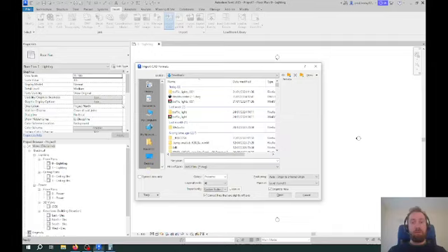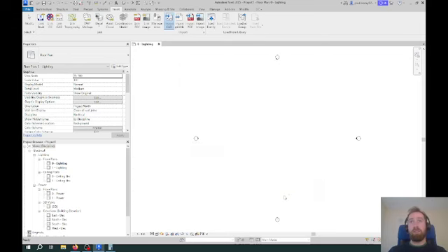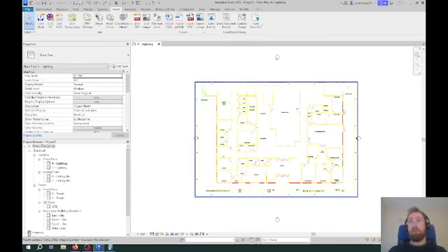So going back into Revit, select our drawing, custom factor, scale it by 60 units, import it, and I'm importing it at level 0 here. If you have multiple levels, you can put it at different levels, but 0 is okay. It's also going to import to the origin. We can do center to center if it'll place it in the middle of the image. So now here's our building imported.